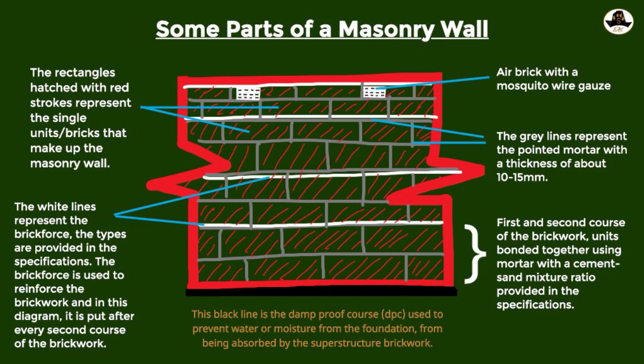And then looking at the bonding of the bricks is like how the bricks are arranged. So that one is called the stretcher bond, because the stretcher is like the length of the brick, then the width of the brick is called the header. So the stretcher bond, that's the length of that brick. And we have many other types of bonds.